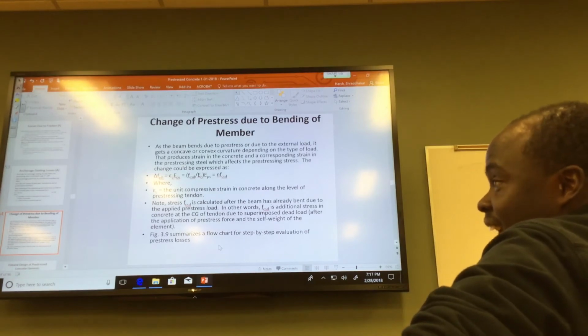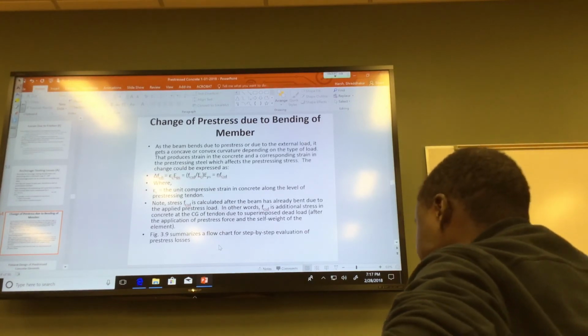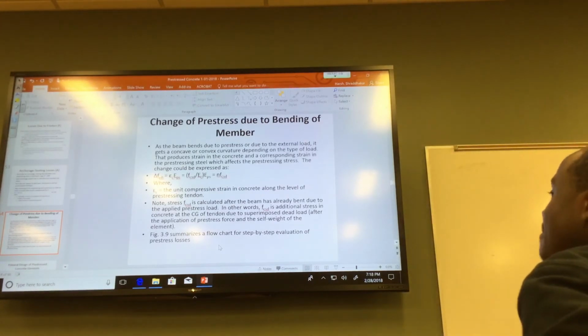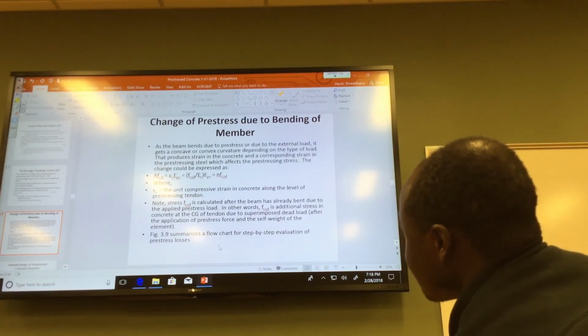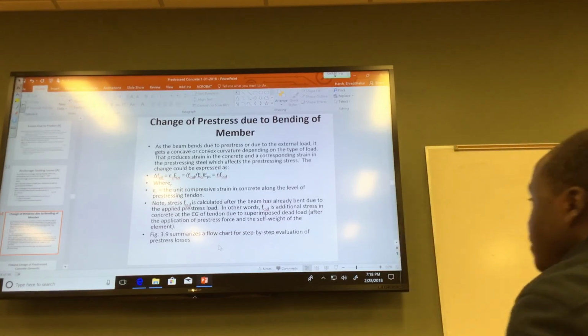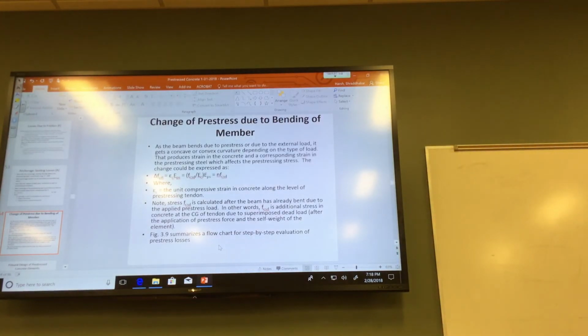No, live load is generally transient, but some live load is not transient. That's the problem. So you have to say, okay, I'm going to use 10% of the live load as a permanent load or sustained load. Then I will understand your logic. But if you put the whole live load, that is an overkill. That was my assumption, by the way.